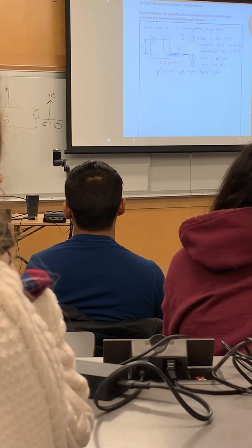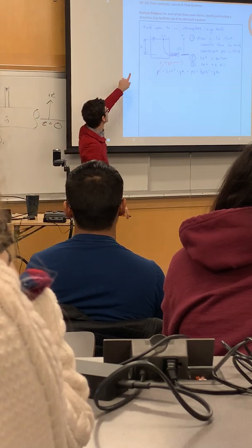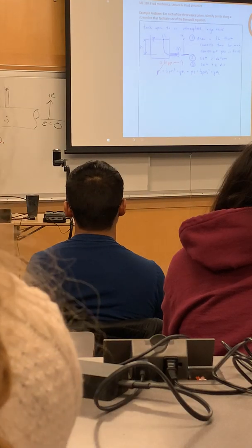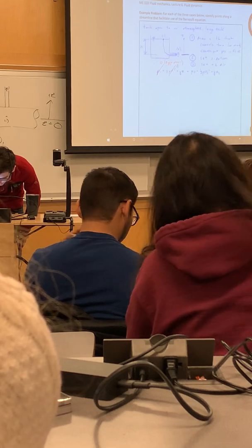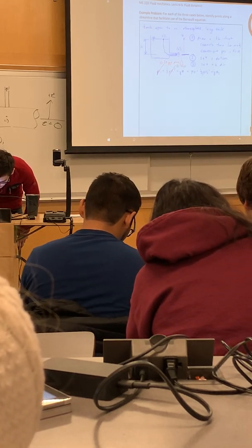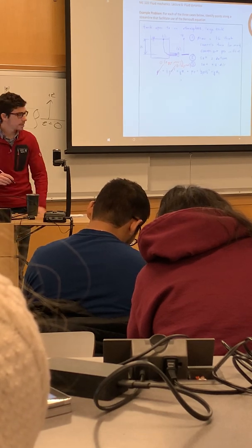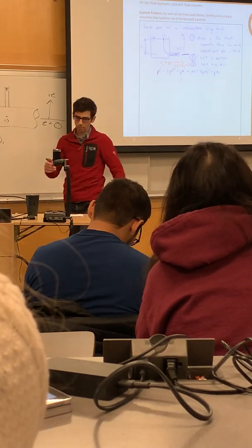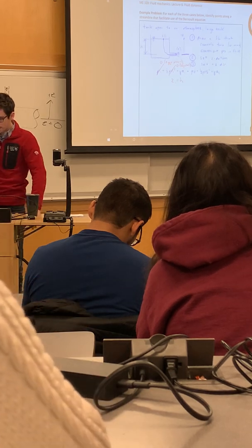It's constant, right? So dH/dt is 0, but H has a value that is constant that is given to us. Okay, an important distinction. So the velocity is 0, right, because of the large tank. And then gamma is Z1, not 0. Z1 is equal to H. Right, so that makes our lives quite a bit easier.